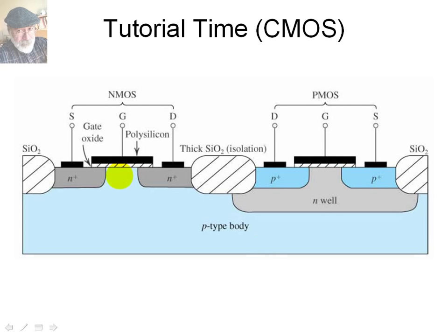One of them is an N-channel transistor, the one on the left, and the other is a P-channel transistor, the one on the right. Please observe that the N-channel one is built directly on top of a P-type body. Here we will enhance the channel region and make it rich with electrons borrowed from the source and the drain wells. The opposite happens in the PMOS.